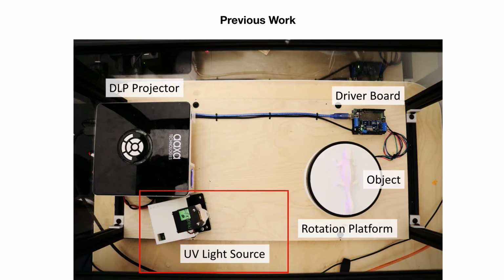In previous work, we used a UV light source, a UV LED, pretty much a point light source that just illuminated the entire object. So we had to go through an entire erase step, saturating it completely, going to black, and then using the DLP projector to selectively desaturate the cyan, magenta, and yellow color in this photochromic coating to achieve a specific texture.